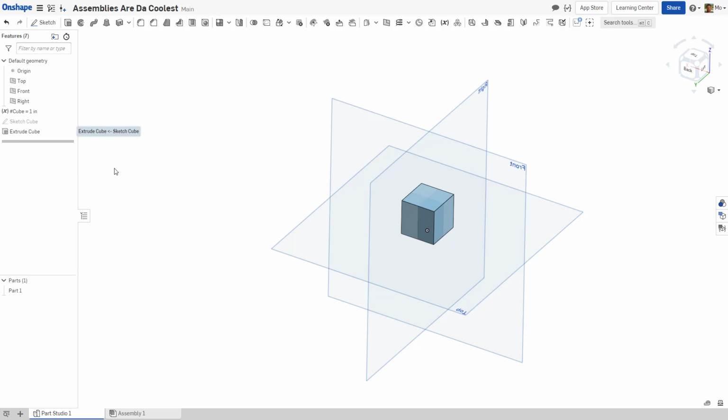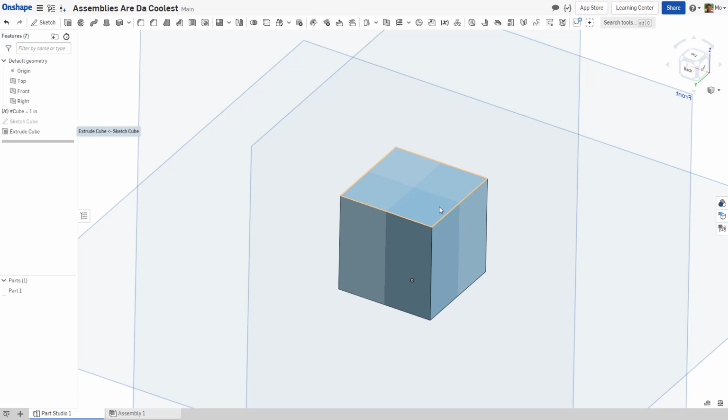And now, let's move on to those lobes. I'd like to lean further into our review of what we did last time. And so rather than extruding some circular profiles, let's use a revolve. That means that we'll have to draw some rectangles on top of our cube and revolve those rectangular profiles along an axis between these 2 midpoints.